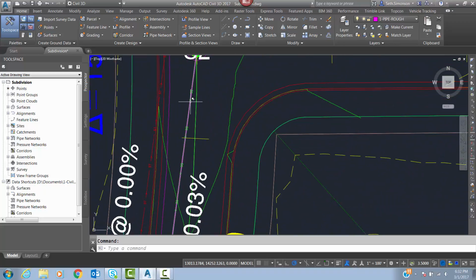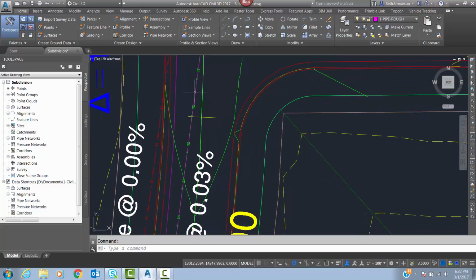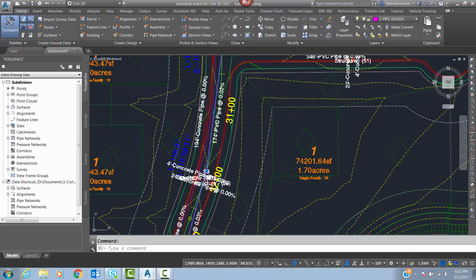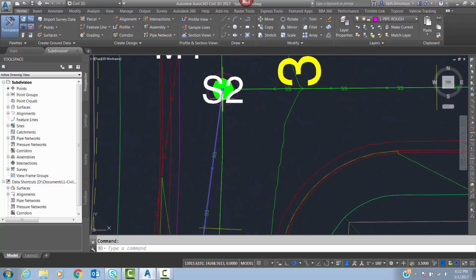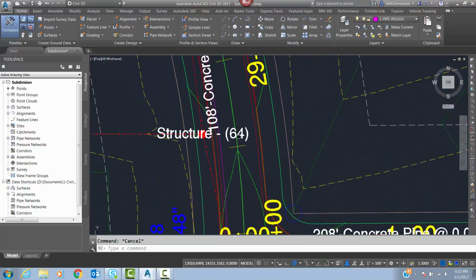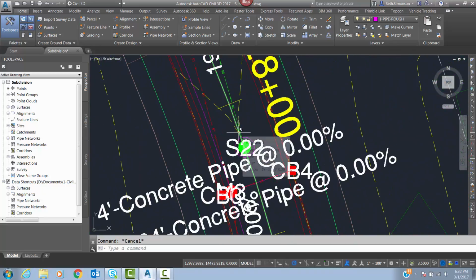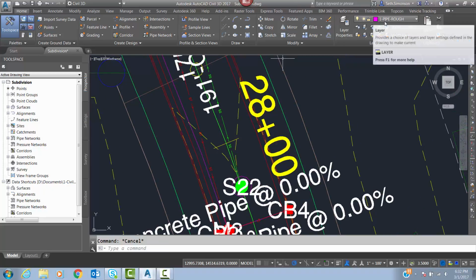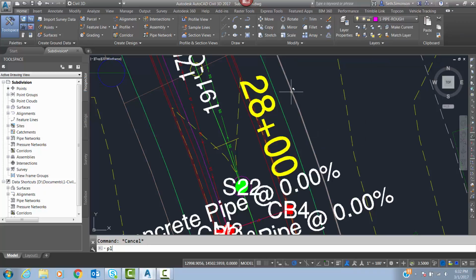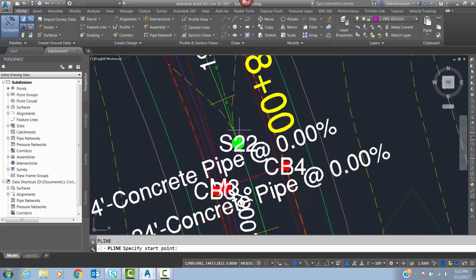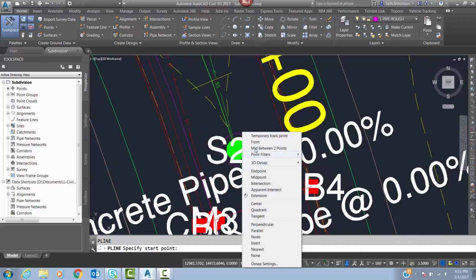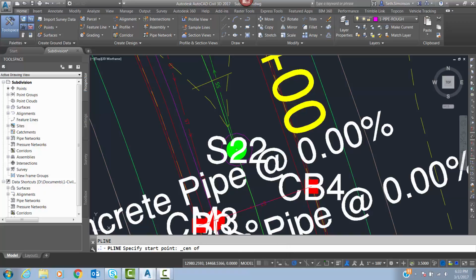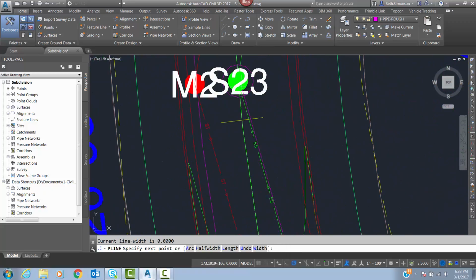If you've already got the polylines on top of your sanitary sewer pipe, then you're already good to go. You can just offset those. So here I do have my sanitary sewer pipe with the line on top of it, but up here I do not. So I'm going to have to draw that in manually. So still on my 1-pipe rough layer, I'm going to draw in those polylines, just going from this point all the way down.